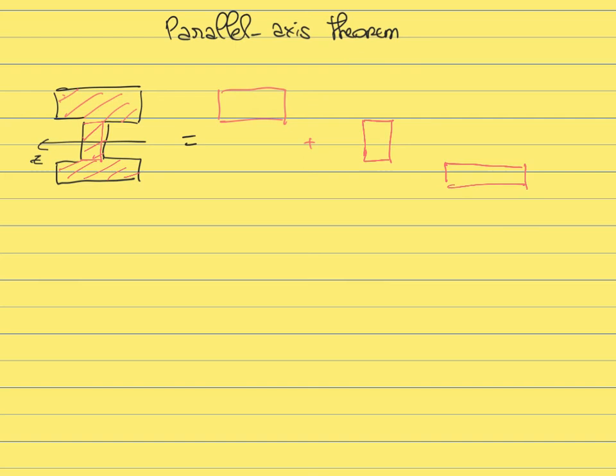So you can decompose the total I-beam into 3 rectangles like this that are located about the same z-axis. So the idea is that if you do this, you decompose this complex shape of the I-beam, the cross-section of the I-beam, into a series of 3 subsurfaces that are all rectangular and for which we can apply the expression that we previously saw.